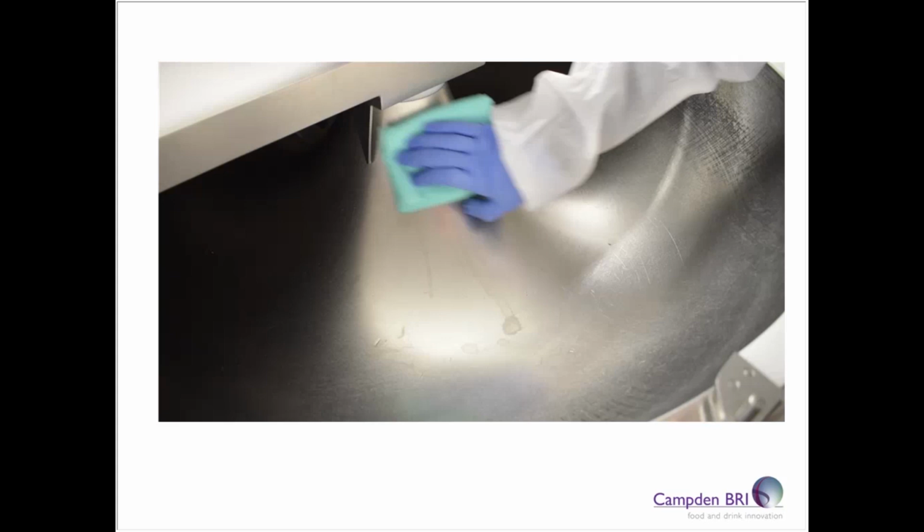The staff must know what they're doing and be trained correctly. It's also worth mentioning that taking off parts to clean also takes some time, so considering downtime when you're purchasing a piece of equipment is really important as well. In the specific example here, you can see that it's difficult to get to the very back of the equipment. So the operative is able to clean the front end, but not the back end. So we have a potential design issue here.